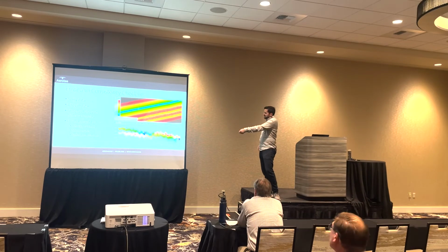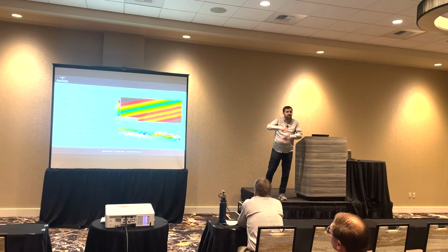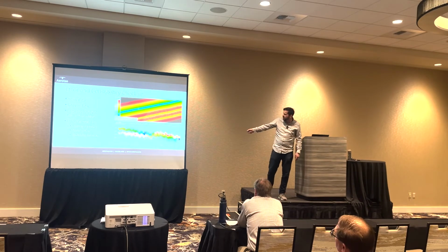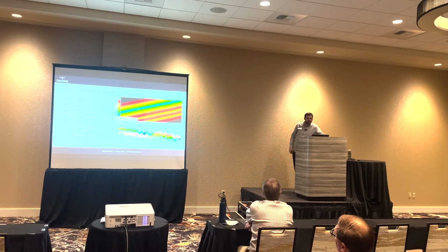At the bottom, what we're seeing is the profile view of where those two swaths overlap. You can see that there is a lot of overlap over here. They look pretty tightly put together. But over here, that red data, the high scan angle, is starting to deviate from the other one. This is a phenomenon that we see in other drones and multiple LiDAR systems, and it seems to be happening in some DJI L1 systems more than others.